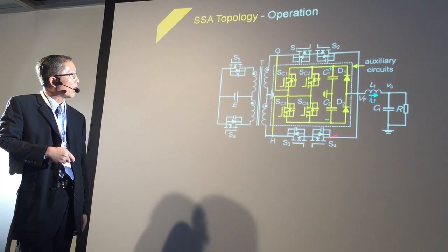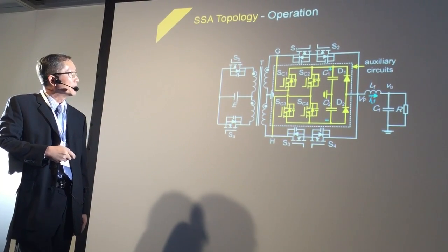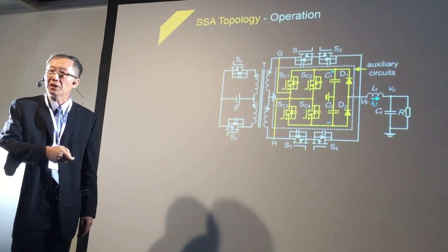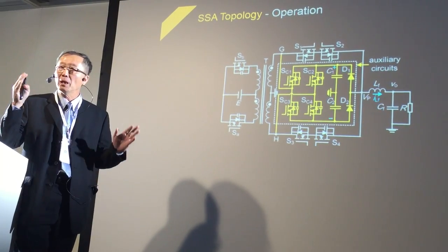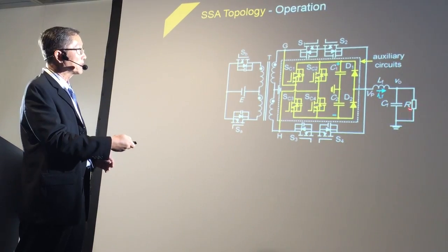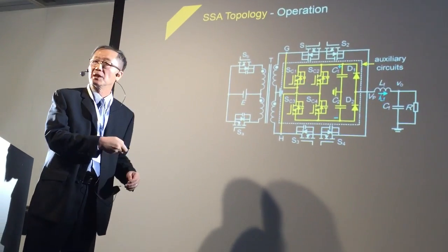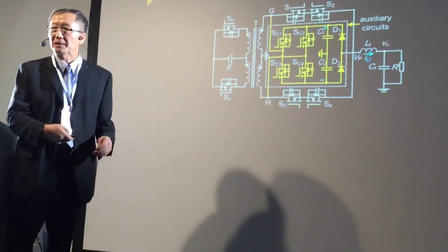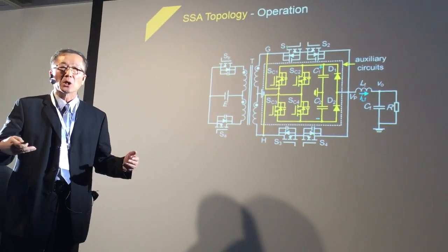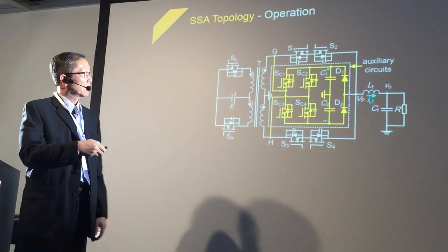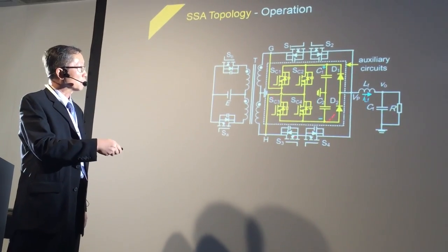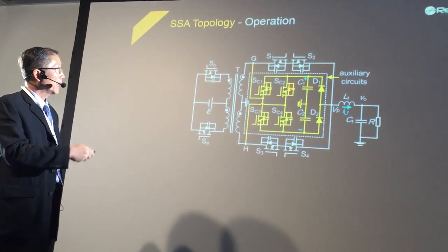And very important, the heart of this invention is a bidirectional energy tank to store the energy from either the primary side or the secondary side. Because we have a load impedance that can be very inductive, like a speaker, a mechanical type of resonant circuit, the energy can come back and be stored in this part of the circuitry.